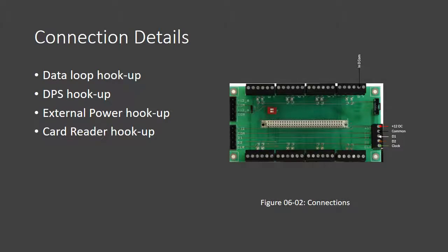One thing to note about these connectors is you'll notice that there are 8 connectors on the board, but the board will handle 16 inputs, and the way that is possible is because each connector can take 2 inputs. And so starting at position 0, you would have N0 common on the second position of that connector, and then you would have N0 positive connection, N1 positive connection, and N1 common connection.